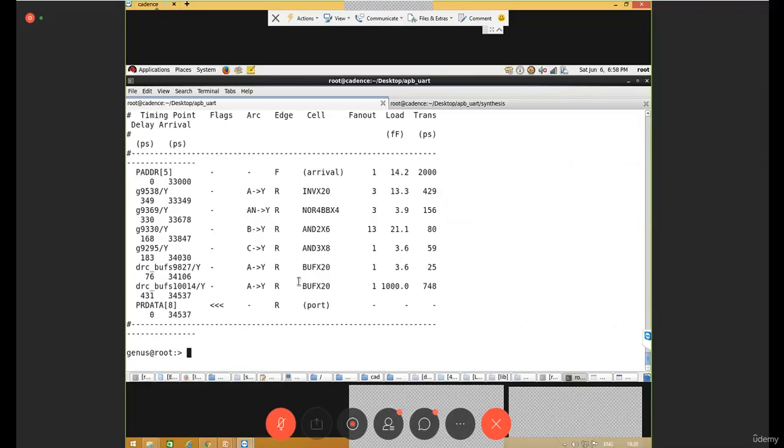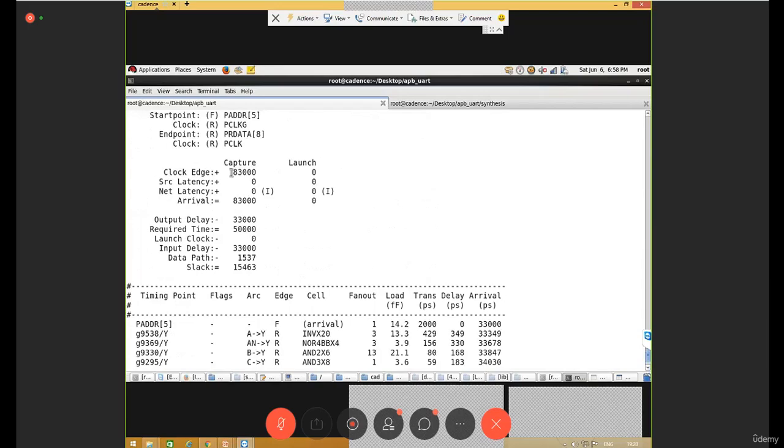And here you can see my slack is positive. What slack is, I'll be telling in the STA sessions. But as of now, you can see that whatever numbers we have given in the SDC file are taken into consideration while calculating the timing. So if my slack is positive or 0, that means it is a suitable delay value for that input port or output port.